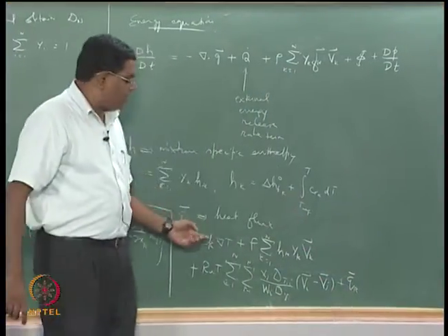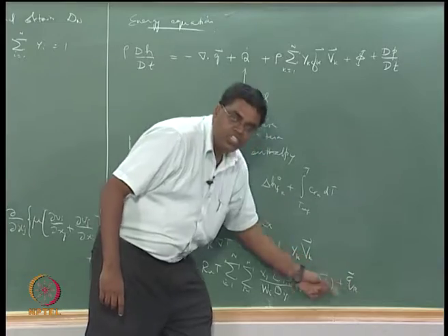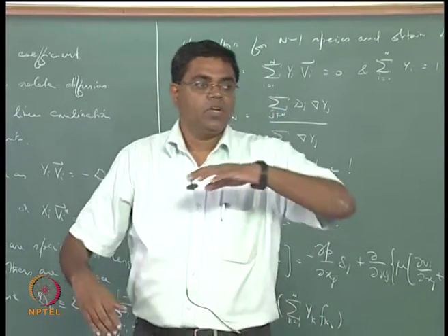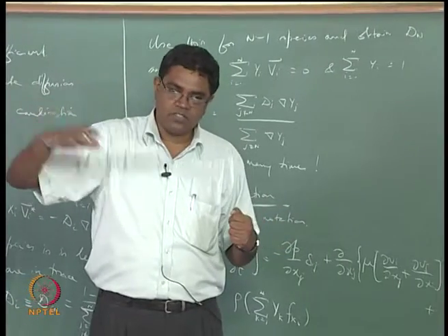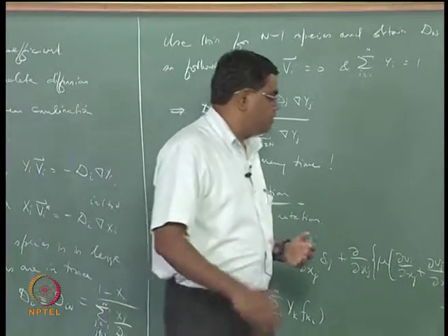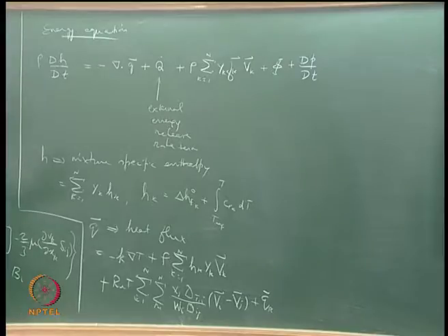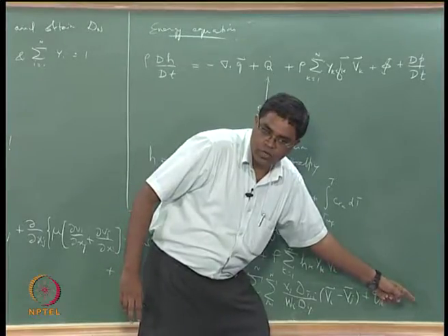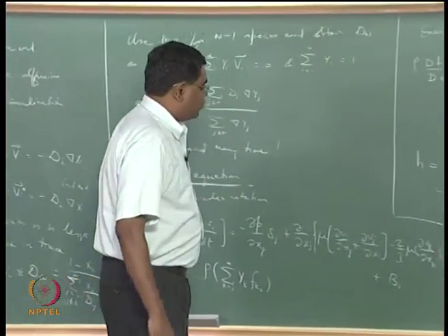So what we have had so far here is only the conductive heat flux, therefore you also have to add a radiation heat flux, and the radiation heat flux will have to be modeled based on Stefan's law, and if you have to look at an enclosure or something of that sort, you have to have shape factors coming in and so on, absorptivities and emissivities and all those things. That is something that you want to do separately, but at the moment you just have to plug in, but keep in mind that it is going to depend on temperature. Okay, so it has a T to the 4 expression, and that could be an unknown because temperature is an unknown. Okay, so you could plug in an expression for that if you want.